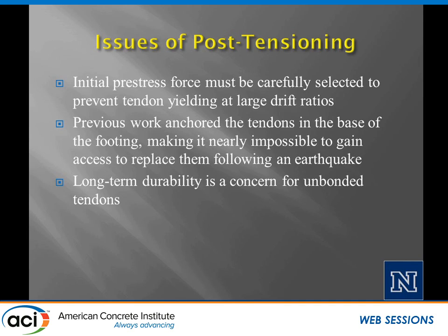And one of the more haunting problems, and our studies don't necessarily address this completely yet, is that long-term durability is a concern with these unbonded tendons. If the column becomes cracked and we can get chlorides into that system, what happens with these tendons? Now, it helps that the system is compressed under a dead load, which is certainly different than what you would find in a beam or a typical cold construction joint in a beam. But there's still issues relative to this long-term durability.